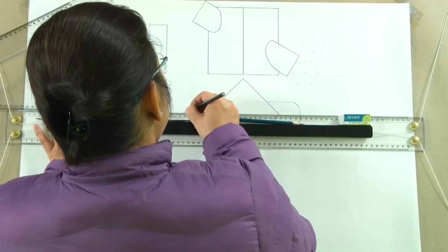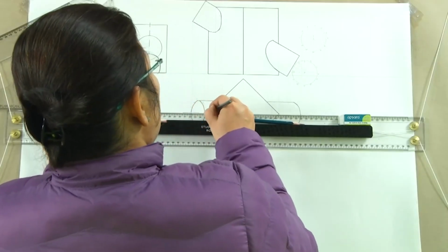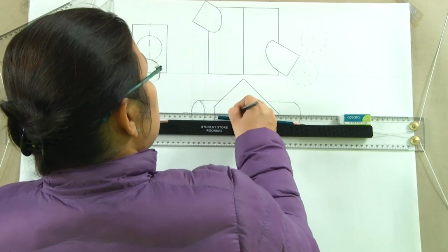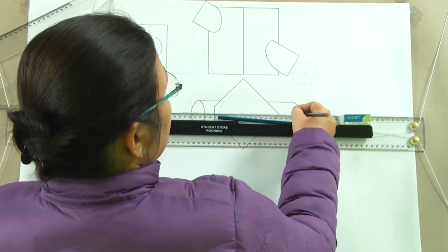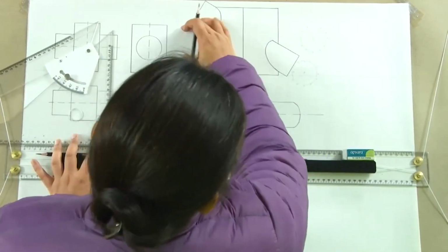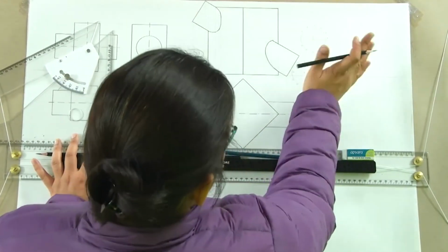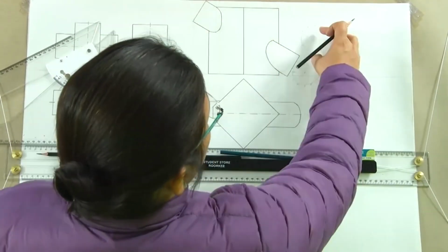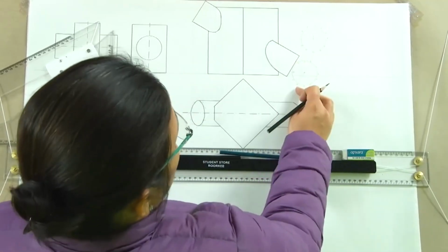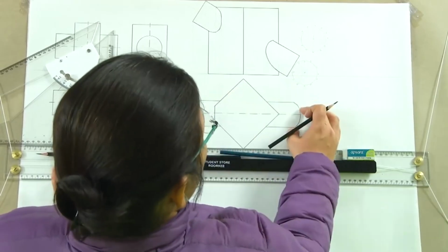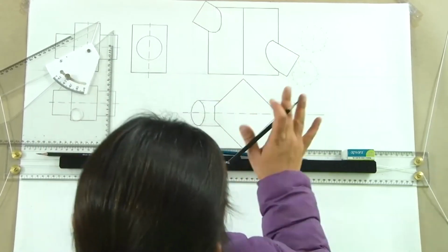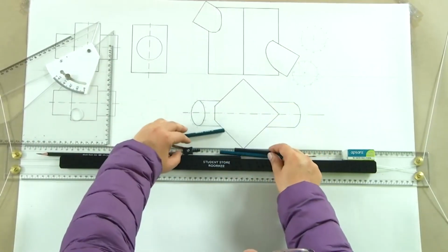So, what we are going to actually do when we are drawing this intersection of surfaces is assume the solid was kept in simple positions, so parallel to both the reference planes or parallel to one and perpendicular to the other. Which is what we had done, just assuming it was parallel. Since it was simple, we just had to incline it, we just needed these horizontal projections and then those vertical projections back. This is what we are doing and getting the projections in place for any solid for that matter.